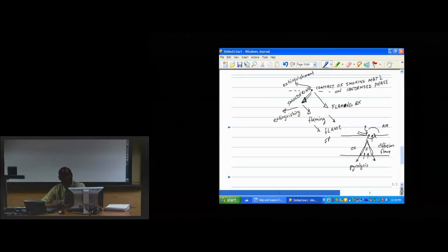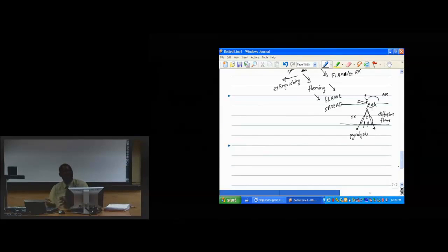We have large-scale flames sweeping over condensed phase fuels, where the flame heat transfer processes are liberating pyrolysis gases, or decomposing this cellulosic polymeric material into smaller hydrocarbons that are then burned in the gas phase. So while scale is important, in some sense the abstraction and the picture are quite similar.